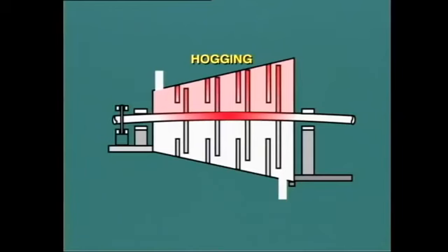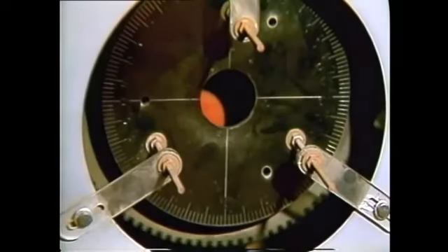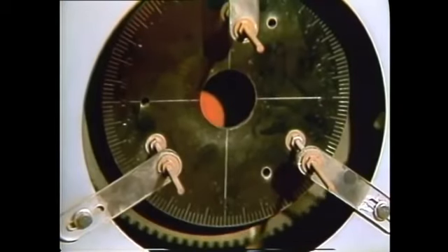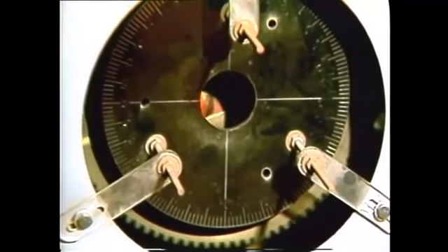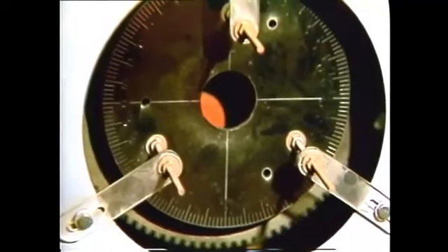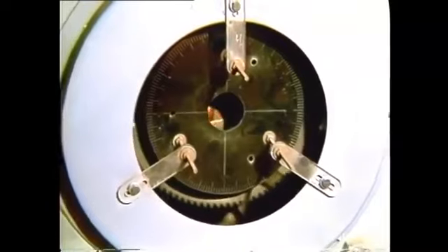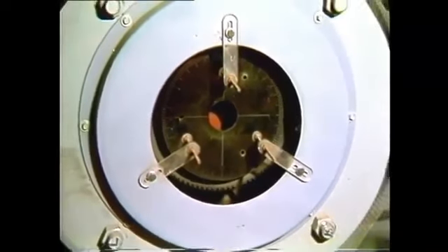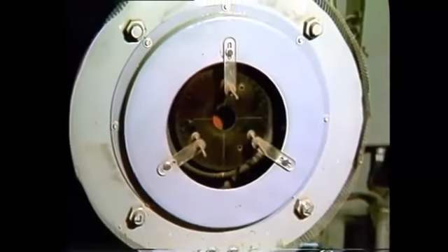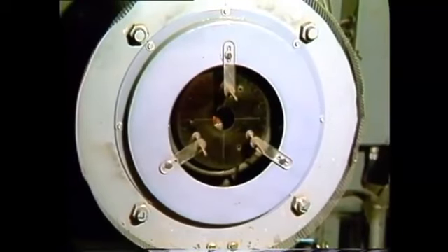Imagine trying to start this machine when there may be contact between moving and stationary parts of the turbine. To prevent this problem, it is essential that the rotor be placed on turning gear immediately after the unit is taken out of service. This ensures that the heat is evenly spread around the rotor and there is consequently no chance of distortion. It should remain on turning gear for several days at least if a long outage is contemplated.